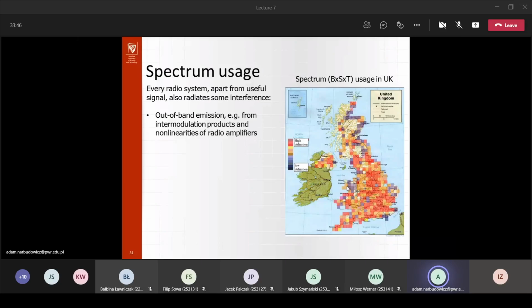in addition to operating at 2.4 gigahertz, it may generate an additional signal at, for 2.4, let's say 4.8 gigahertz, so double the original frequency, the first harmonic, right? And even though the signal might be very small, it can still contribute to increasing this noise, right?